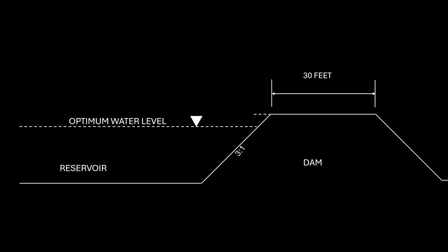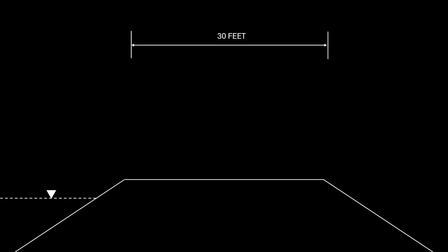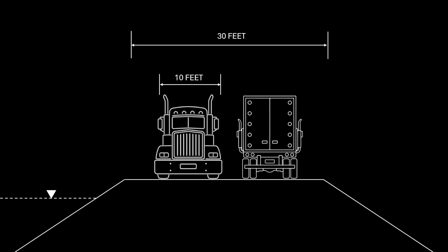Let me set you up for what's about to come next. You're looking at the dam geometry, the overall shape of the embankment, the cuts and fills, and where the 324-foot water level sits on the cross-section. Up top, I've kept about 30 feet of width, enough for a two-lane road and a strong, stable crest.